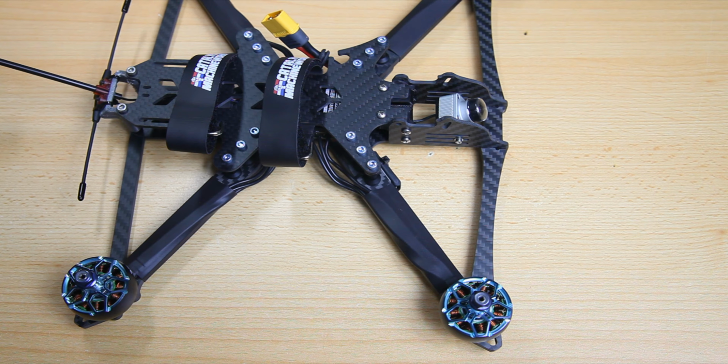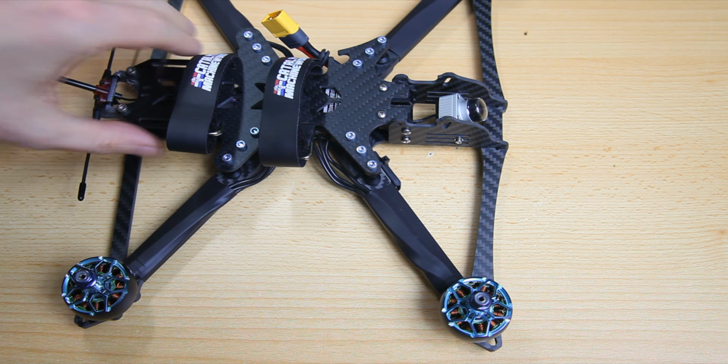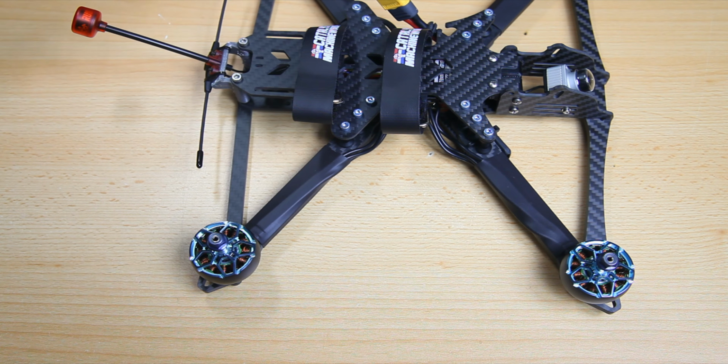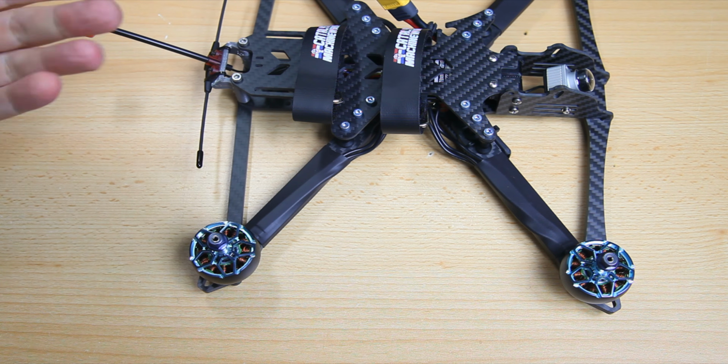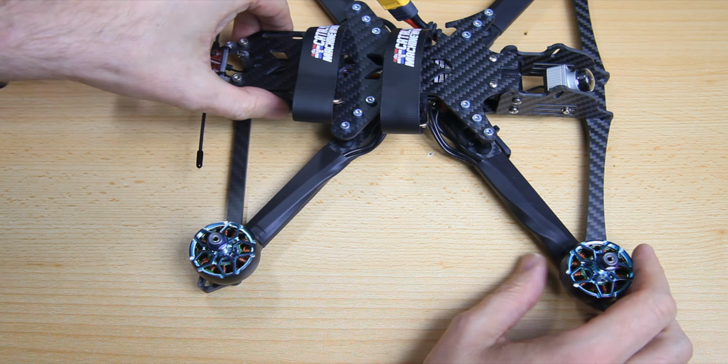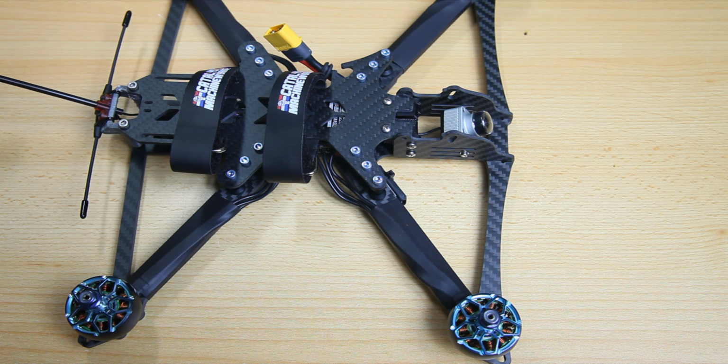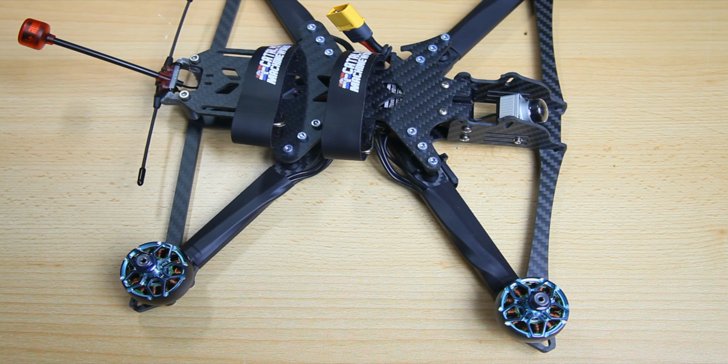And you might find the same thing, that this isn't motor 1. If you try spinning up motor 1, a different motor spins up, and that'll never fly. So in this video I'm gonna show you how to solve that. And particularly in BetaFlight 4.3 and newer, that's become a lot easier. So it warrants a short video on how to change the motor order on your quadcopter. Here we go.